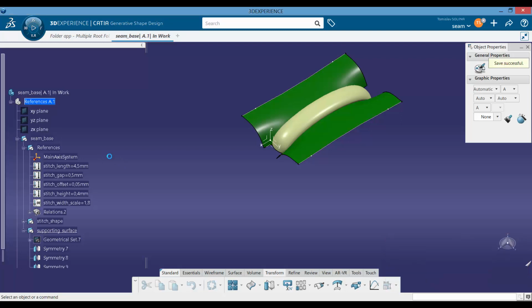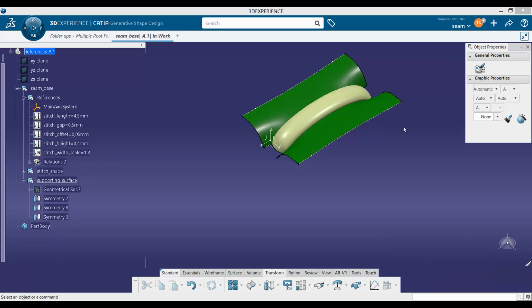Let's say first, making a user-defined feature from this element is actually quite trivial, as it doesn't have a real input in geometry except those parameters. We will simply pack everything as a block so that later we don't have to cope with the whole history or scroll through it, so we have one feature out of it.